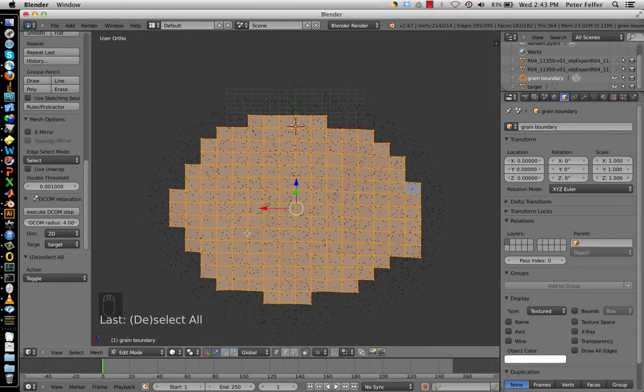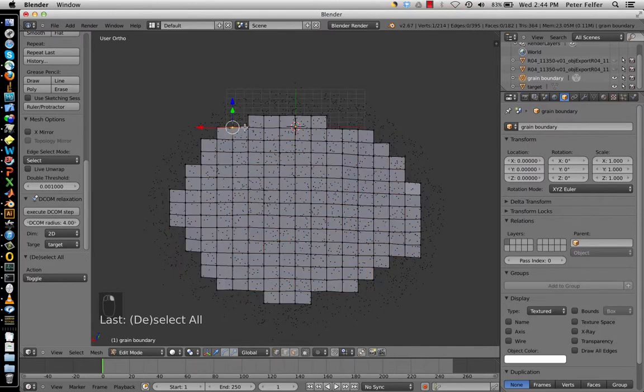If you want to do some visualization, it's maybe advisable to clean the mesh up a little bit, so you can, for example, go and create some nicer faces in the corners so you don't have the ear standing off. But that doesn't actually make a difference for the analysis, really, because the approximation is that tangential continuity.